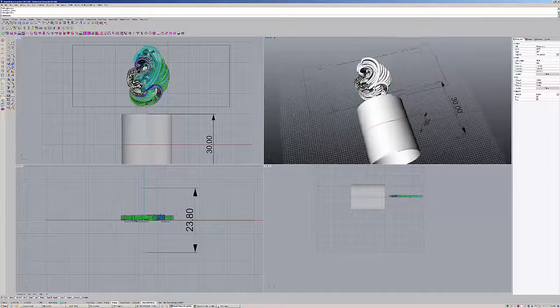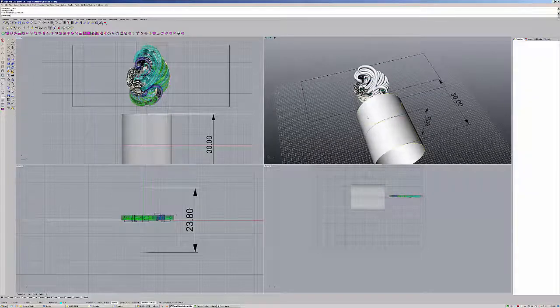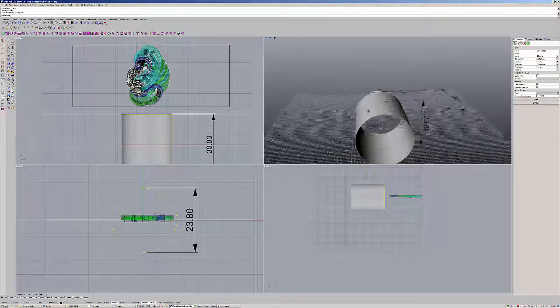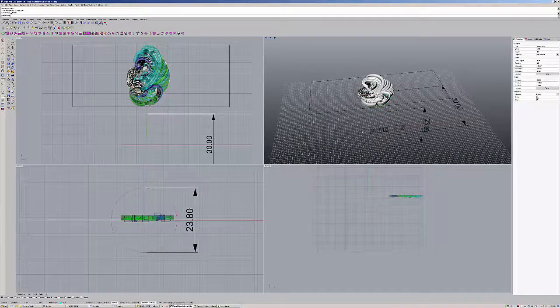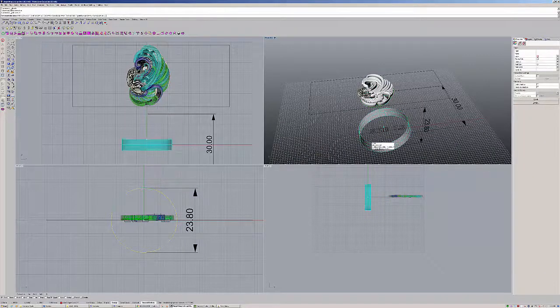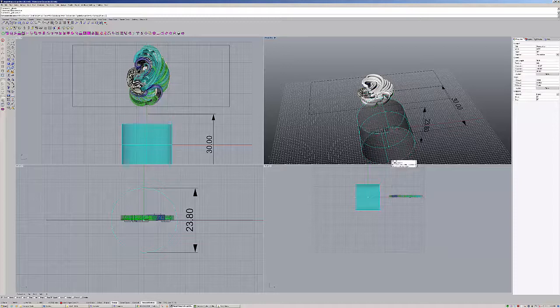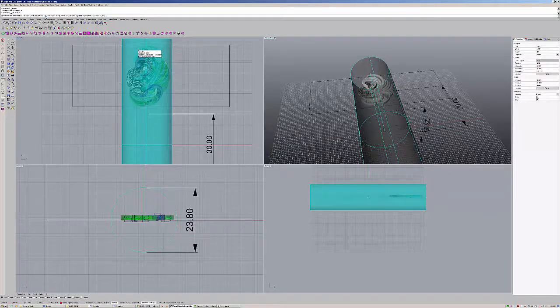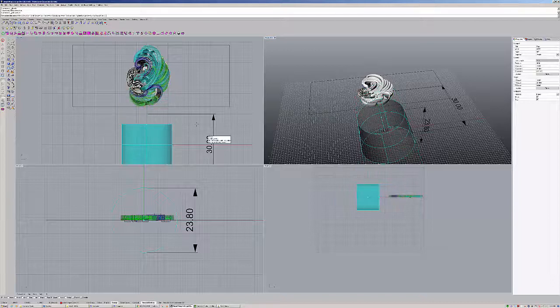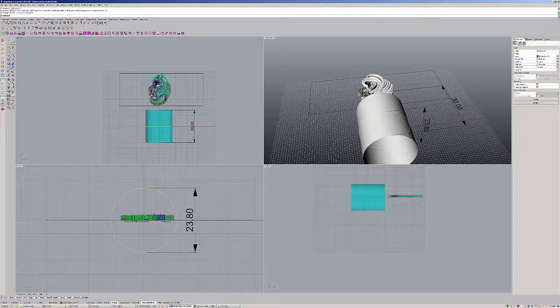So basically, we created a cylinder here, and the way we did that was I have a finger-sized rail and I extrude it in both directions, and we want it 30 millimeters. We want it not to be solid, but both sides, and I enter 15 millimeters, which gives me 30 millimeters in total because it's 15 millimeters in one direction and 15 millimeters in the other.